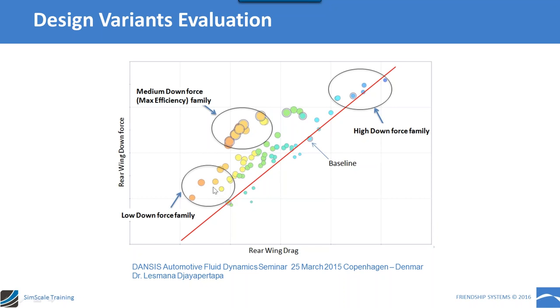And here, if we see, we have low drag with approximately low downforce, and this is exactly what we need for a high-speed circuit like Monza, because we need to make sure that your car is really fast in straight lines and you don't really care about the downforce, sorry, because you have only straight lines.